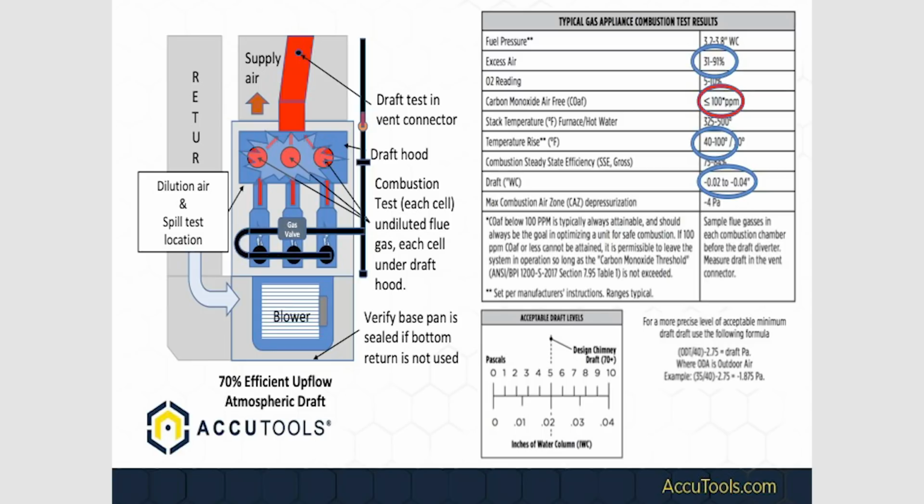You can download that. A couple other things on differential temperature testing. Second most important thing on an appliance, you want to be in the center of the range. You don't want to be at either end, the high end or the low end, because we can either cause condensing in a non-condensing appliance, or we don't leave any room for the filter to load up with dirt. So again, the combustion analyzer can be used to measure the differential temperature with a couple of nice Fieldpiece K-type thermometers.